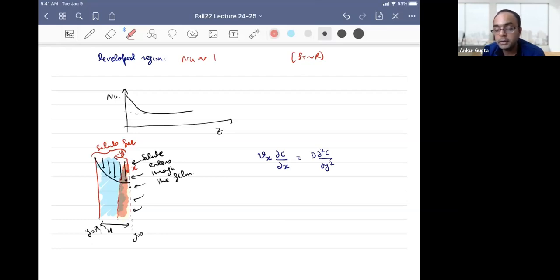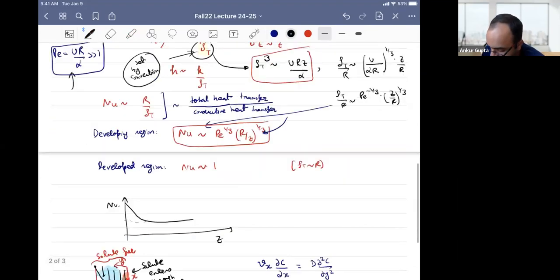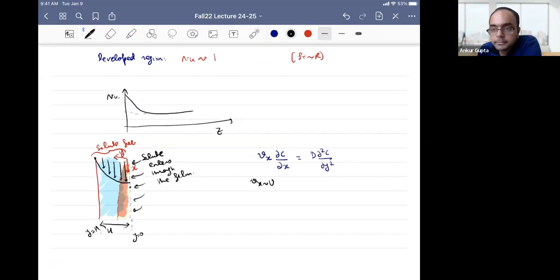And why is that important? In the boundary layer, is there any no slip right now? No, right? There is no slip because it's just at the fluid interface, liquid air interface. So my Vx will simply be u. I do not need to worry about any no slip or linearly scaling like I did here at the fluid solid interface. I can simply do Vx is u. That's it.